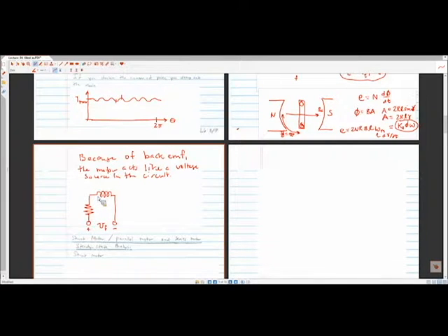It's because there's a lot of analysis of transformers and also electromagnetic systems in a coil form, and every time you have a coil, you have an inductance system because you have a long length of wire. So the electrical inertia of that system is large. Right? So any type of coil is going to have resistance. We'll give it RF, inductance LF, and then we can label the current going through this field circuit.